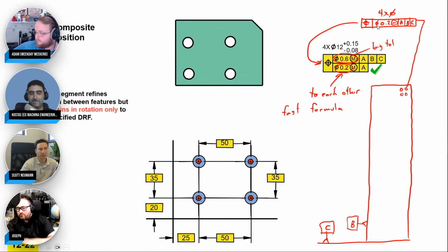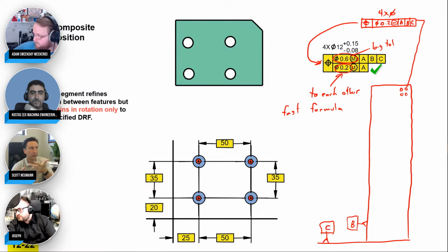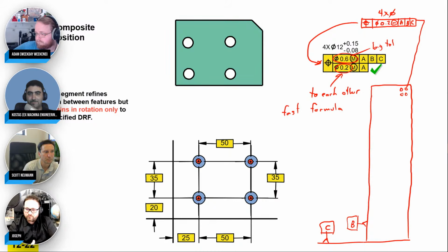And that's what I teach people. If manufacturing is good with the red one, oh yeah, good with that one, right? 0.2 relative to the datums, fixed fastener formula. But then you've got this one in your back pocket. It's usually for larger structures like big weldments or chassis or housings or something where you have a lot of components mounting on there, and they can kind of float and do their own thing as long as this better bolt up and that better bolt up and that better bolt up, but they can kind of shift off of your global reference frame a lot more. So cool. This is so cool. I love it.